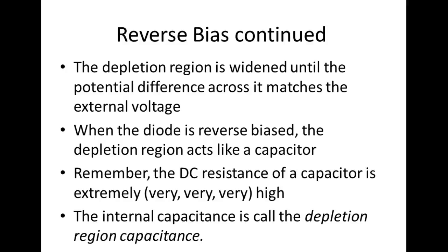Reverse bias condition, the depletion region gets what? Wider. Because that's what we're doing. If we have a depletion region and now we're sucking electrons this way and we're sucking holes that way, right, you understand the depletion region just gets wider. But there is a path. There is current flow through there. So we can't say there's no current, but the current flow is going to be determined by temperature.